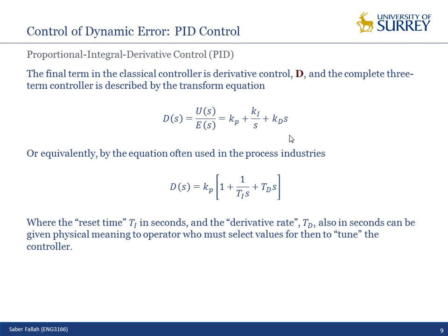But as we saw again from the example, the integral controller can add overshoot to the system. So we need to somehow deal with it. So we can use the derivative controller as well to add one degree of freedom to our control system design, as a PID controller. What's the advantage?